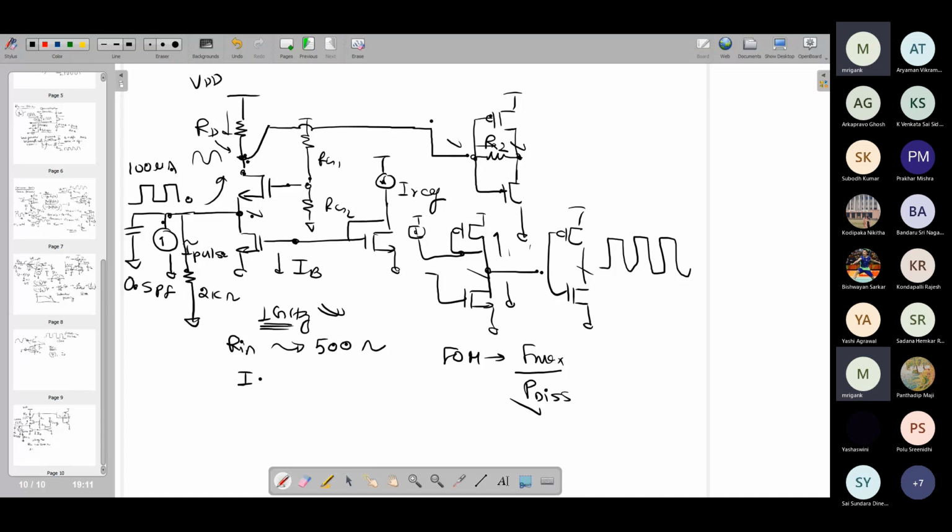So again, I can give you the design flow exactly step by step, but given the discussion that we have had on all these stages, common gate, common source, etc., you can figure out how to do it. In this stage, it is possible to use an active load also. For example, in the common gate stage, I can also use a direct connected load, right? You can use the direct connected load, and along with that, you can use a current source load.